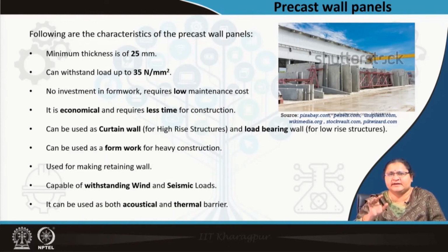So, the skilled person should be knowing which panel to take and lift it and put it in which location, which after which, like the adjacency of the panels are to be known. So, this is very crucial. You require skilled labor. One should be able to read the drawing and find out the right one. So, all panels will come with their numbers on site.